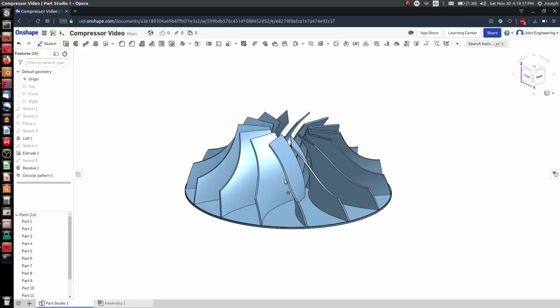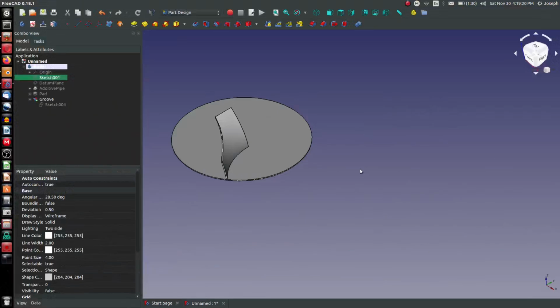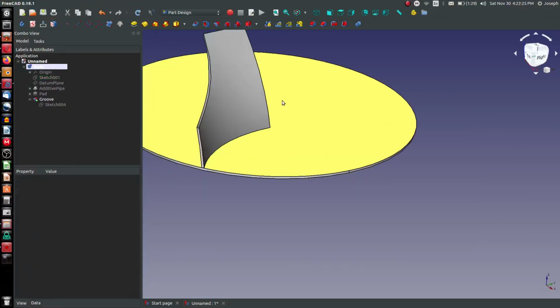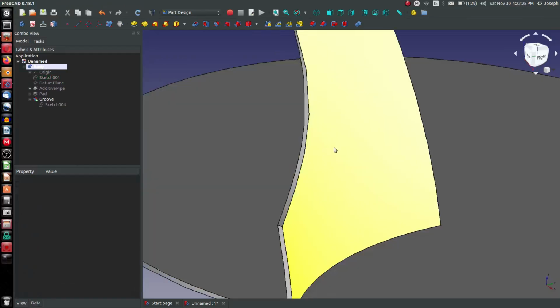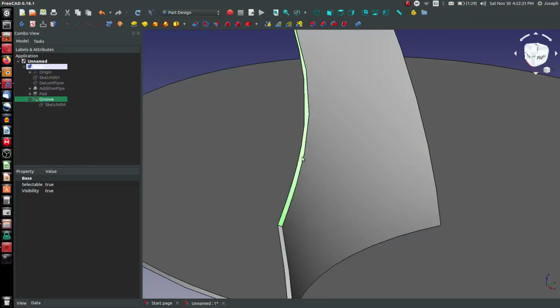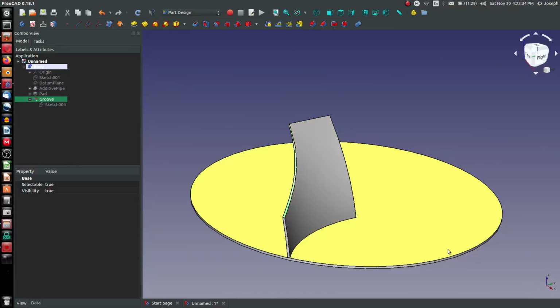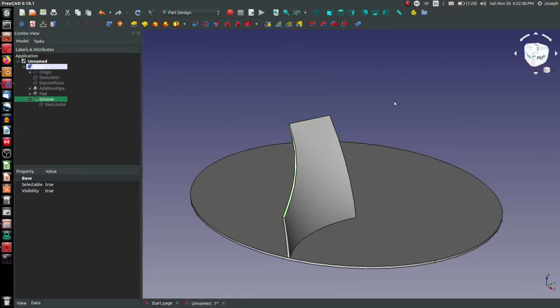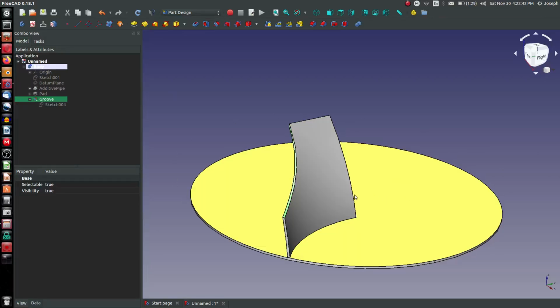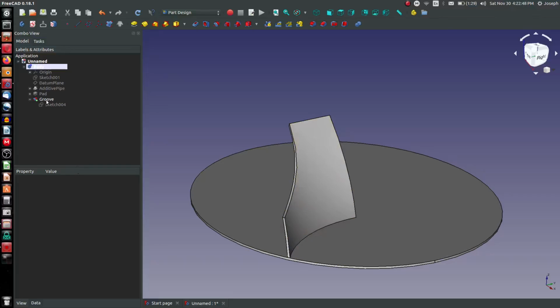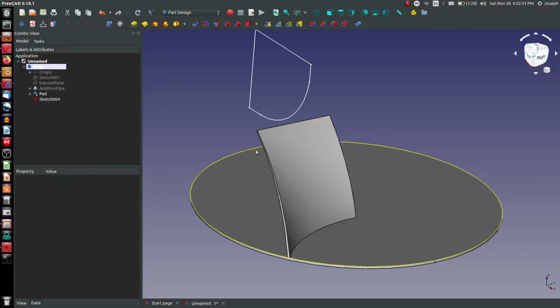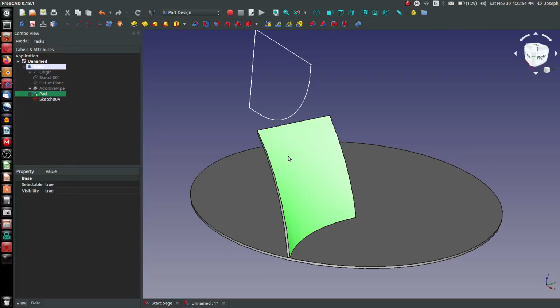Next thing that we would do well for is replicating that in FreeCAD. Now as I go to pattern this, one thing that I'm seeing is I've done my additive pipe with a cut to help shape the blade. I've realized if I try to pattern this groove, it will just pattern the whole part 14 times. SolidWorks and maybe OnShape gives you some options to pattern it differently, but in FreeCAD I'm going to temporarily delete my groove and just pattern my additive pipe for my polar pattern. So with this highlighted, I'm going to choose polar pattern.